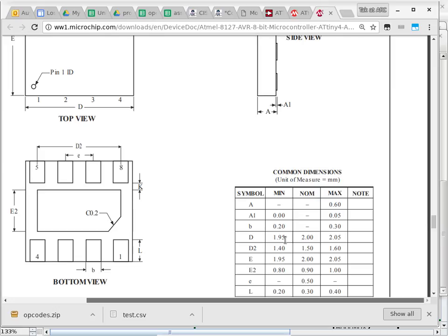Could you measure your heart rate? Yes, you can. But you will need LEDs and some feedback mechanism, so you need to have LEDs and a photodiode or phototransistor to read back how much light is either going through your finger or getting dispersed back to the sensor. From that, and you sample it at a certain rate, yes, you can actually check your heart rate at least. They're already talking about blood pressure sensing on the casing of a phone. So when you're holding your phone, you're just doing your usual texting, your phone is actually taking your blood pressure. And these chips can do that.